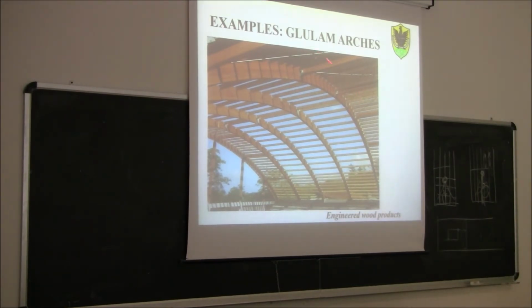Now the remark is that we have one bracing system here. If you look at another bracing system here, 1, 2, and then nothing between. But since we have 2, also these arches in between cannot move too much. How can they move? Because they are connected, you see, with the purlins, with the other arches which are fixed. So this means that these purlins are also important to make sure that the arches in between cannot move, because they are connected with the arches which are in some way fixed by the bracing system. Okay? Any question about this?